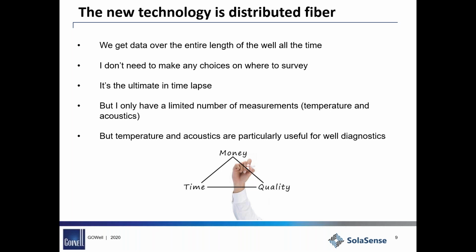However, the actual DTS data itself is a good relative temperature measurement. And this is another way of playing off the strengths and weaknesses of distributed versus wireline. So wireline, that's where I'd be pointing to for my good point absolute temperature, but then the DTS is what's giving me a relative change over that survey interval.